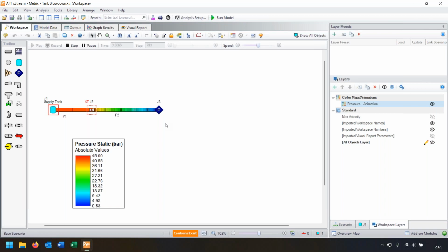The last thing we'll talk about is transient forces, which I don't have in this example, but you can also specify a transient force, for example, maybe at this valve, or a point force, or if you're looking at elbow pairs, how do you have an axial force that acts on it? And again, those forces can be exported into Caesar if you're looking at pipe stress analysis.